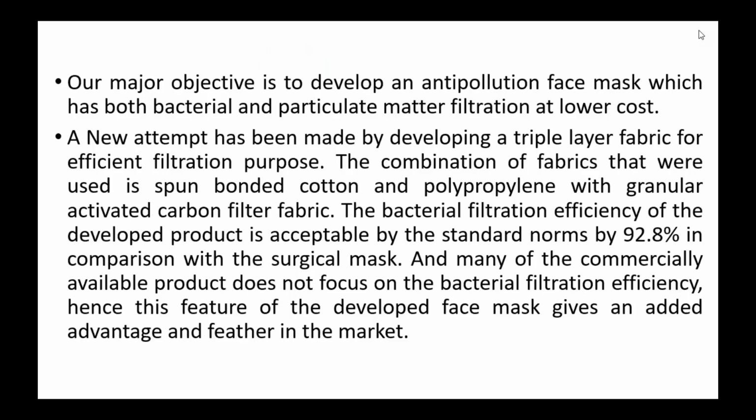So my major objective is to develop an anti-pollution face mask which has both bacterial and particulate matter filtration efficiency. A new attempt has been made by developing a triple layer fabric for efficient filtration. The combination of fabrics used in my research is spunbonded cotton and polypropylene with granular activated carbon filter fabric as a sandwich layer, right? I have used spunbonded cotton fabric as the inner layer, spunbonded polypropylene fabric as the outer layer, and activated carbon filter fabric as an intermediate layer, which acts as a filtering membrane, a sandwich layer between these two.